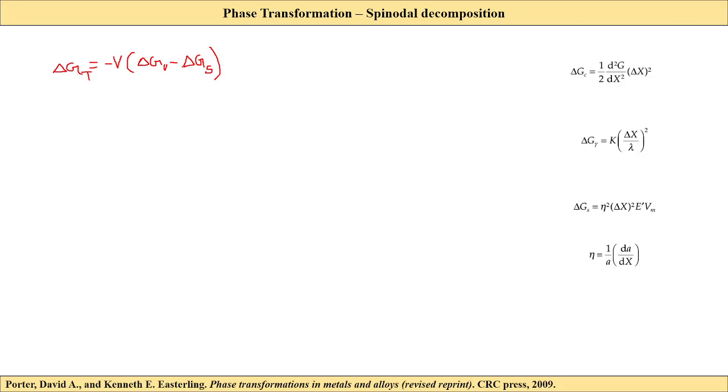Why? Because minus into minus will be plus. So some part of the volumetric free energy is being taken out by the strain energy, because the system needs some energy to accommodate or strain those points. Not the whole part. If it were the whole part, then the system would not form, right?